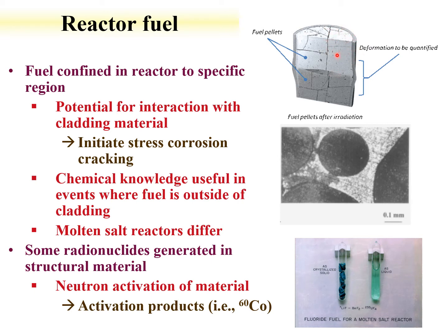Fission products are being formed. They're impinging upon the fuel. They're forming different phases. The fuel's undergoing stress. It can crack. You can have some swelling as the fuel swells, as the fission gases increase. It can push out against the cladding material, and this can drive some potential interactions. One interaction is initiating stress corrosion cracking, where if you have the fuel begin to crack and it's pushing up against the cladding material, that crack can then propagate out to the cladding.